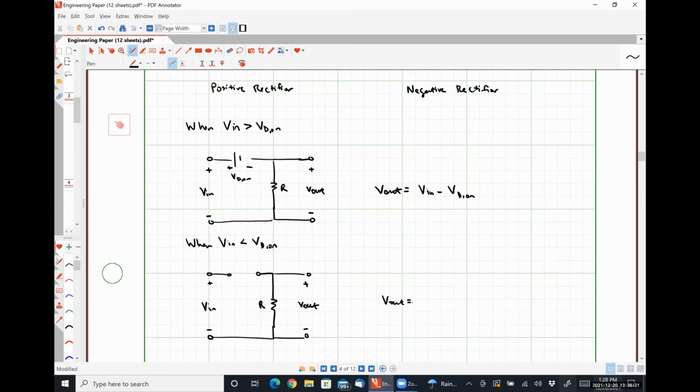Let me ask you a question. Is that resistor R part of a closed current carrying loop? Shaking your head no, you're correct. So if the resistor R is not part of a closed current carrying loop, how much current flows through the resistor R? None. If there's no current flowing through the resistor R, then what's the voltage drop over the resistor R? 0. So the output voltage is 0 volts.